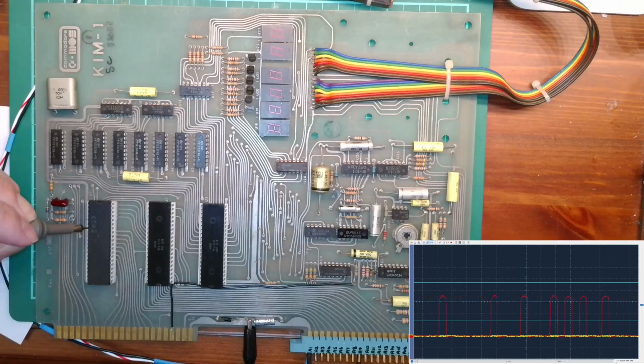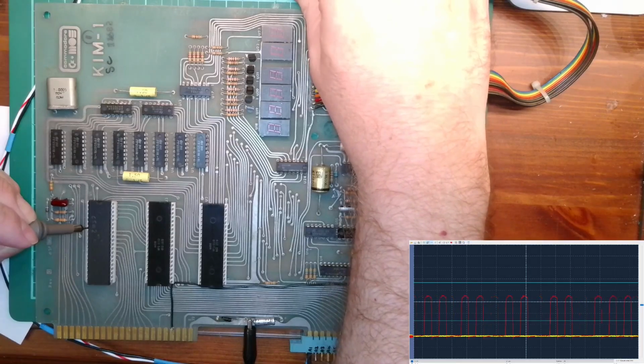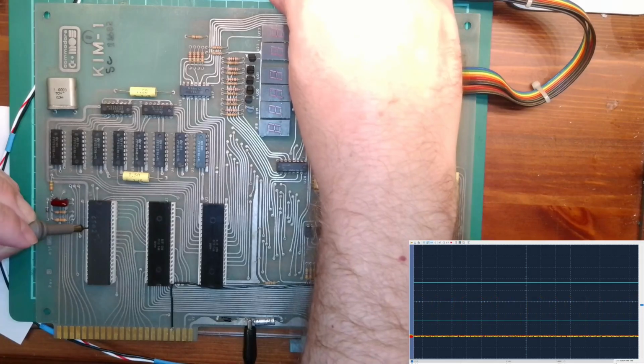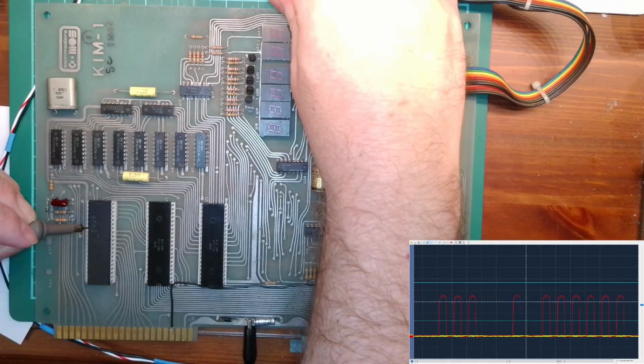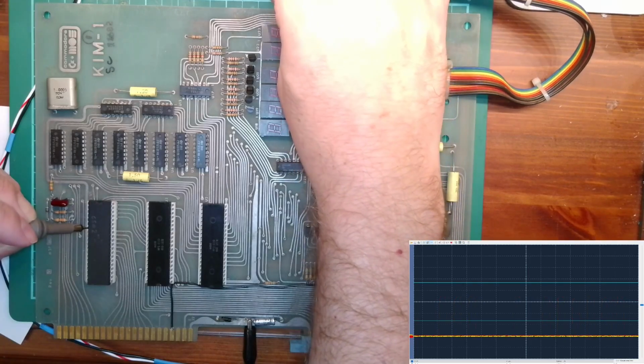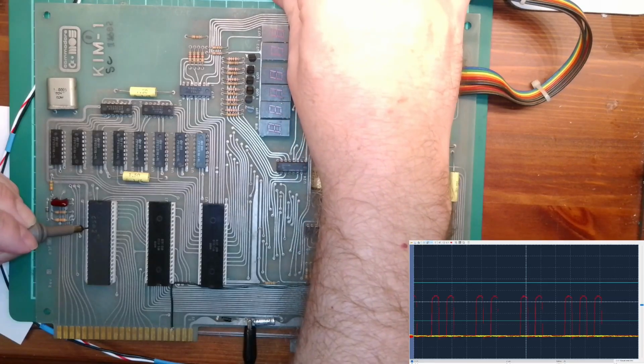It's not necessarily running what we want it to run because the display doesn't seem to do anything. If I press the reset, you can see it's resetting. Go single step, it just stops. Press reset again, and there we go, we get a few pulses. It does about 11 instructions and then stops. I'm not sure if that's because it's got to a single step point or a broken bit of code.